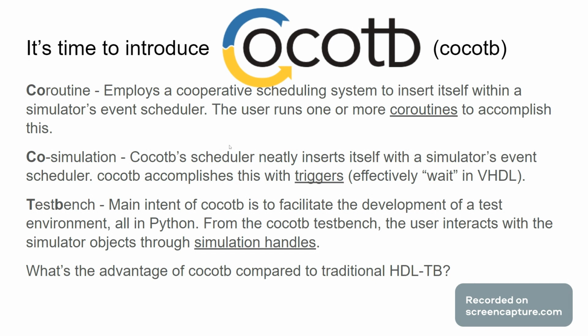In fact, the way it works is cocotb inserts itself into the simulator's event-based scheduler using a system called triggers, which are effectively the wait statement in VHDL. If you're already familiar with the wait statement in VHDL, then you're pretty much already familiar with triggers. It's just a matter of understanding the keywords and maybe the syntax differences, but they effectively do the same thing.